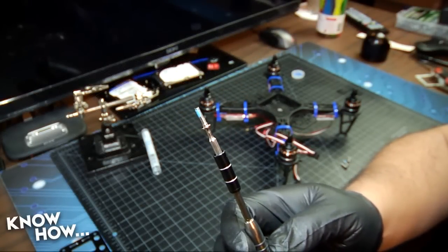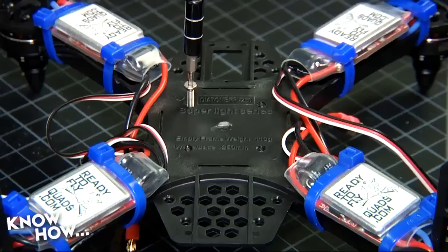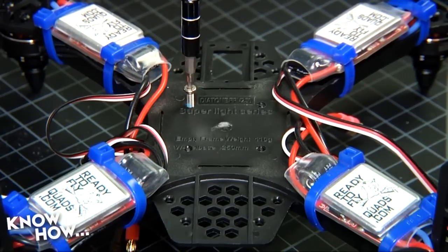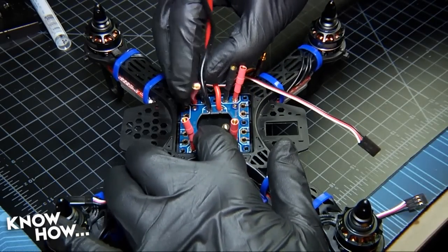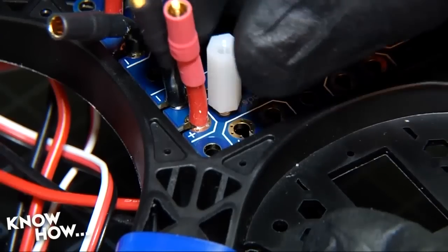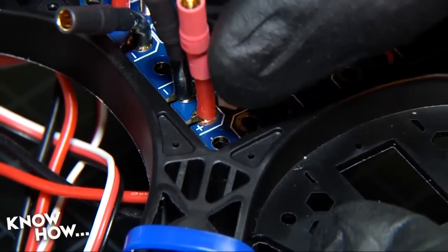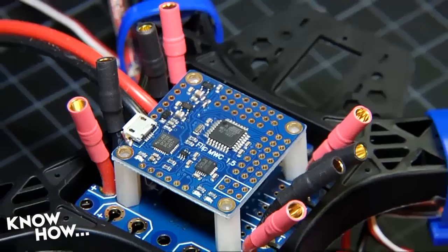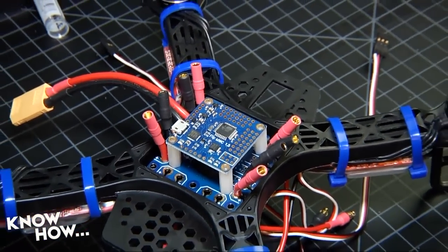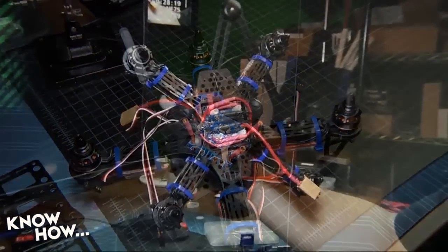With the power distribution board completed, we need to mount it on the frame. Run 4 M3 12mm screws into the 35mm mounting holes on the underside of the frame. Then mount the power distribution board on top and secure it to the screws with 4 plastic standoffs. These standoffs not only hold the power distribution harness in position, but they will also be the mounting point for your MWC Flip flight controller.